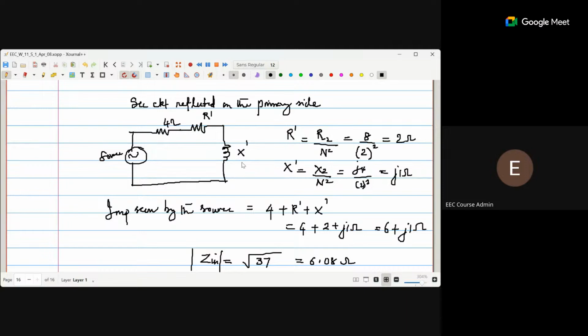So this is again based on that impedance matching. I think it's fine for you. Any clarification? What I did was, ma'am, I took the magnitude of 8 plus J4 and then I multiplied it by N1 by N2 whole square, which is divided by 4. It was coming as something. 8 plus J4 divided by 4 will be 2 plus J. So root of 4 plus 1, which is root of 5. 2.23 plus 4 is 6.23.